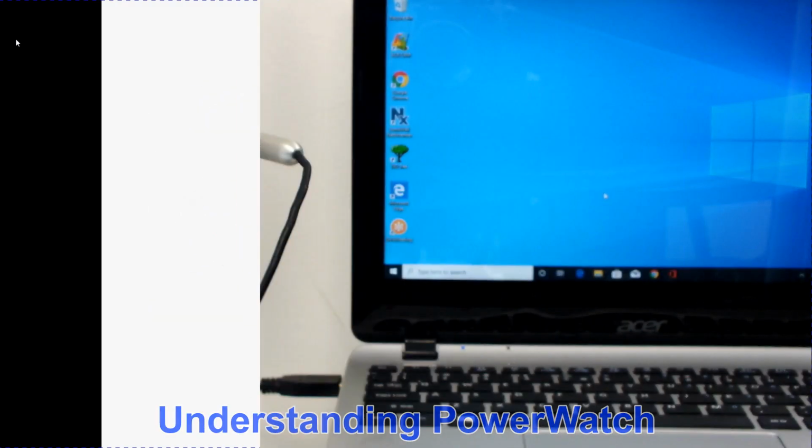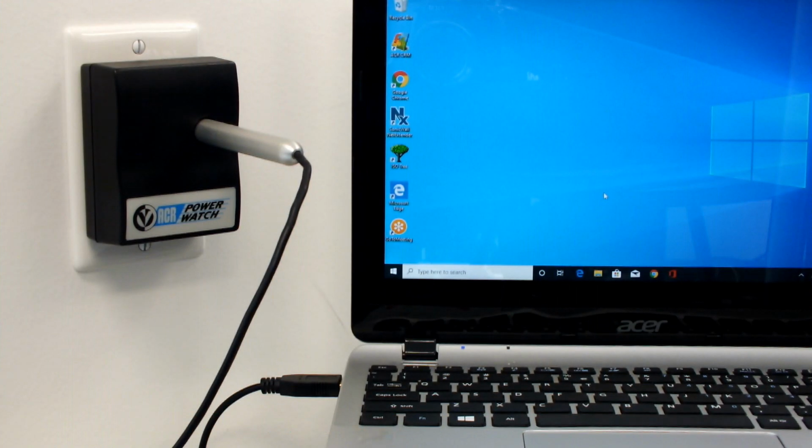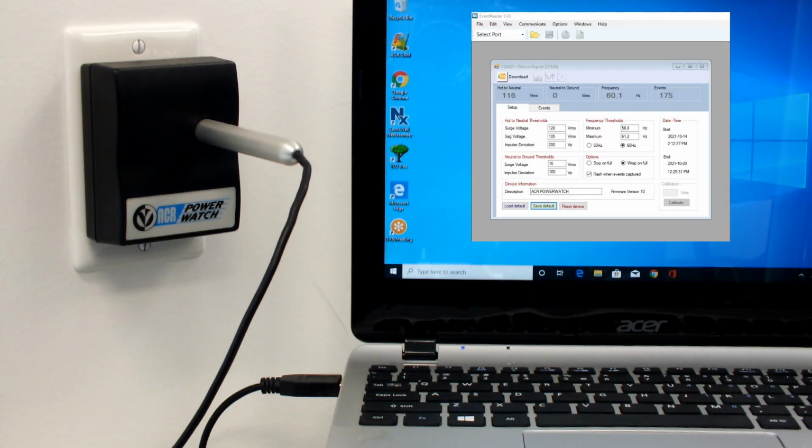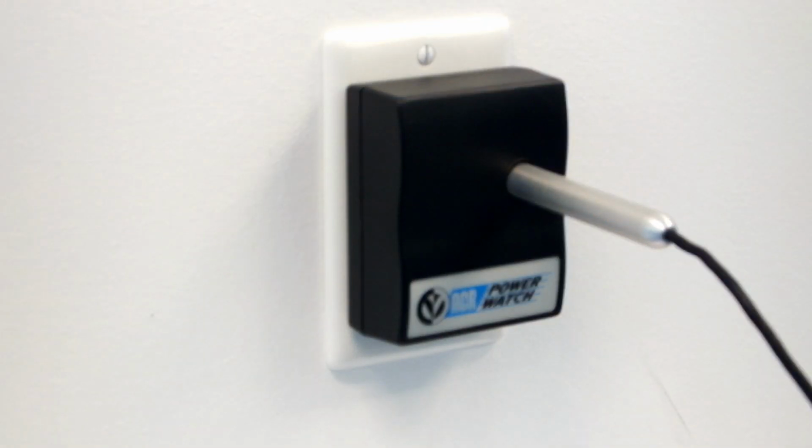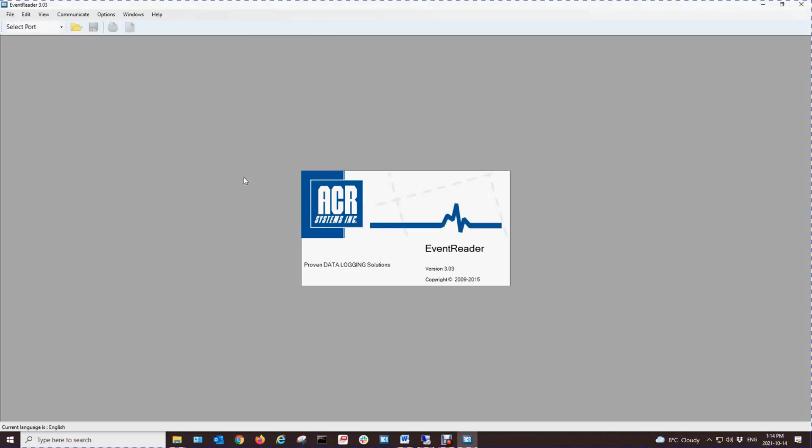In this video, we will examine how the ACR Systems PowerWatch, using the Event Reader software, reports the event's information to help you better understand and analyze the data collected. After the PowerWatch VDR has captured some event data, you can download it and view it for analysis. Start the Event Reader software and connect the PowerWatch to your computer via the LIC Lightlink cable.